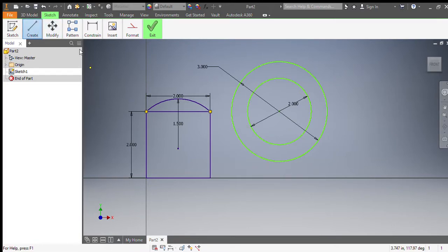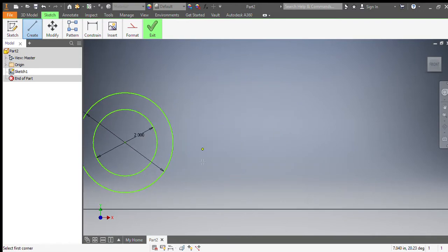Our next tool is the rectangle tool. With this one, once again, you click, let go, and move your mouse, and you can move your rectangle both directions. Notice how I have the 2 boxes again. Both of them represent the length of those sides. So if I want a 3 by 3 square, I'm going to type in the number 3, but instead of clicking enter, I'm going to hit the tab key and type in another 3. Then I can hit enter and it'll be a perfect 3 by 3 square.